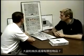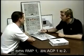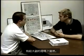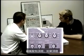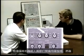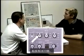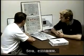What are some items that the first officer and captain also have available? They've got RMP1 and they've got ACP1 and 2. Any lights for the first officer? Sure, the first officer's got the dome light, the right dome light if the dome light switch is out of the off position. He's also got, both the crew have the standby compass light, and then the captain's got the glare shield lights. After 5 seconds, the RAT automatically deploys.